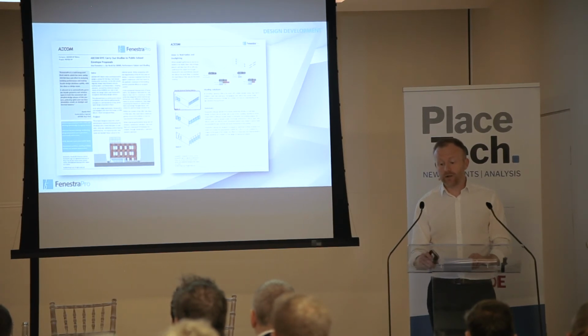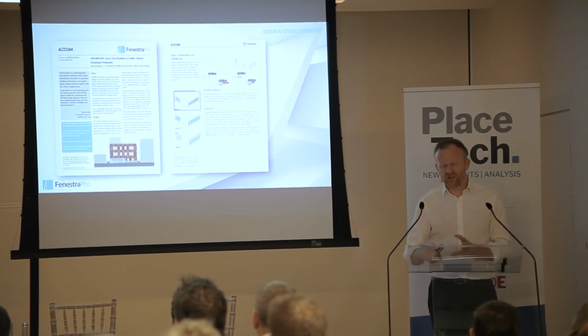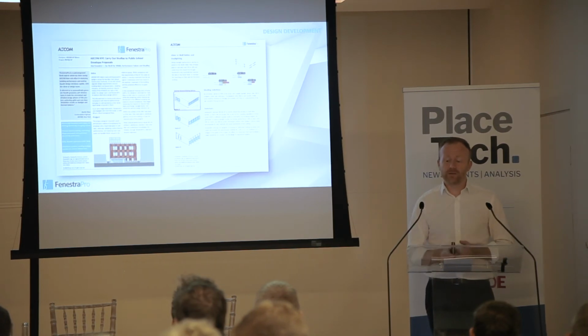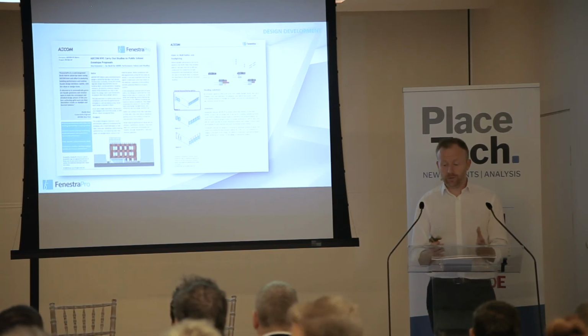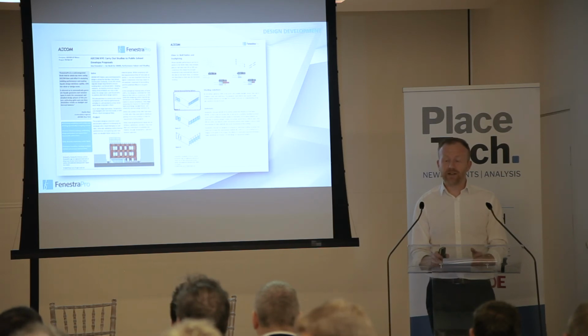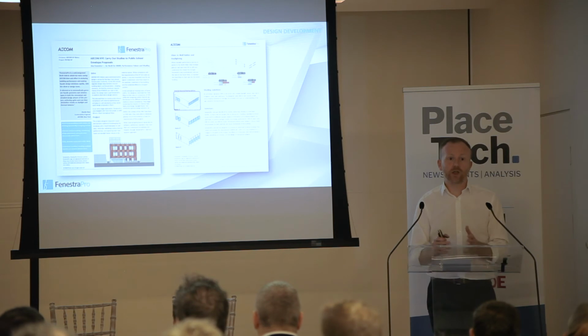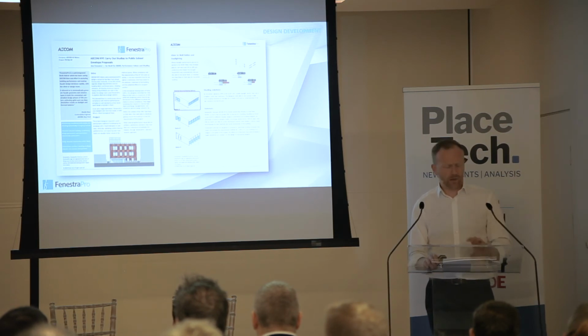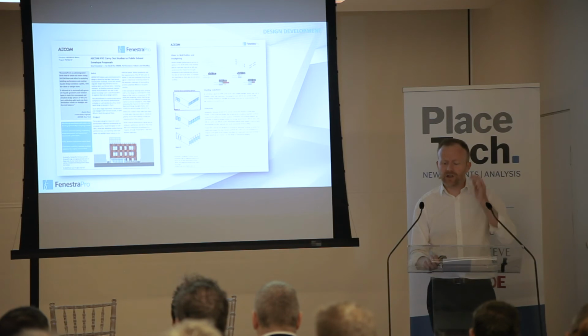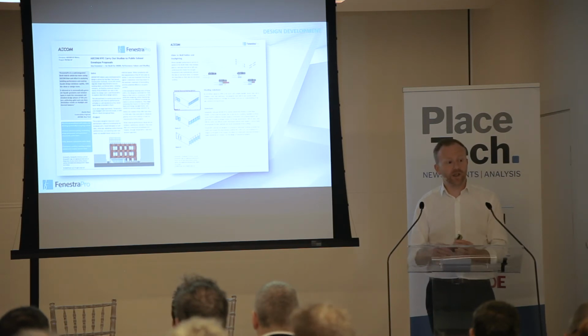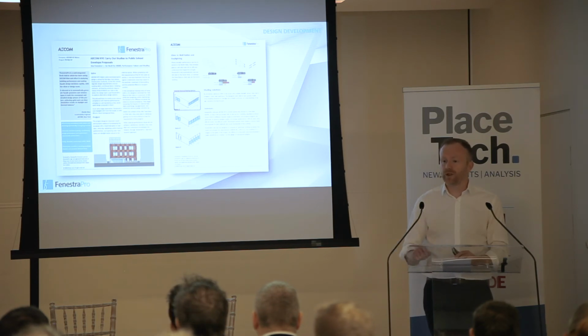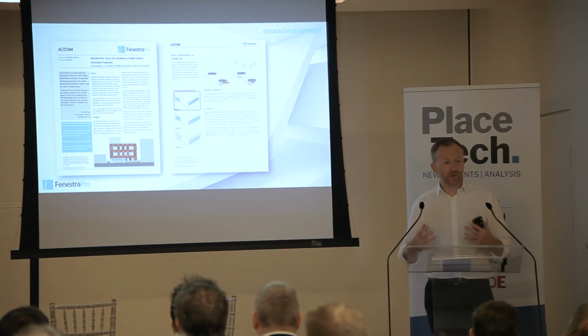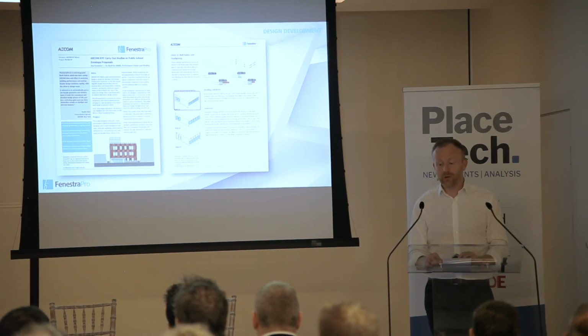AECOM in New York were doing a school. The New York Schools Construction Authority, or something, have some pretty strict parameters within which to work, which FenestraPro was in a real sweet spot for. They had a maximum glass to wall ratio, so you could only have 25% glass to wall, and they also had different fabric specifications and performance requirements. So the team in New York were able to lock 25% within FenestraPro. In other words, their glass would never go beyond that 25%, and they could play around with it easily, knowing it was always going to stay within that.